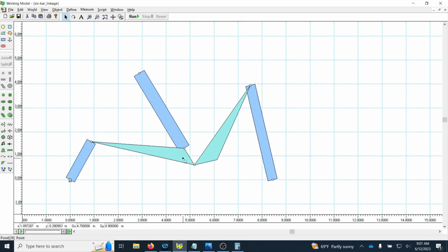And because I put the point here, that is automatically attached to the triangular link which is underneath it. And I can do the same thing for this other triangle. Let's put this point right here. 2 random points, or it could be actually points that we care about. So just to get my point across, if I start rotating my input, but right now I can't because I put a motor here instead of a pin, these 2 points will have to move with that.